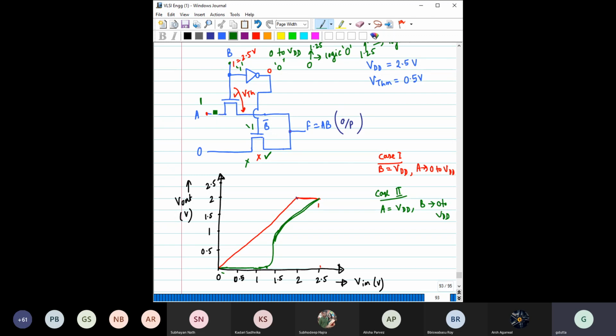If this is the drain terminal and this is the source terminal, as the output voltage is changing, the source voltage is also changing, right? So try to recall the reverse bias between the body and the source. Is it not becoming more reverse biased? You forgot.